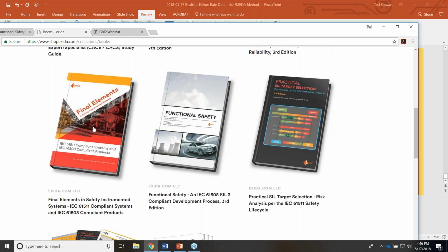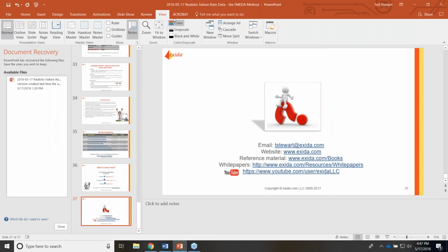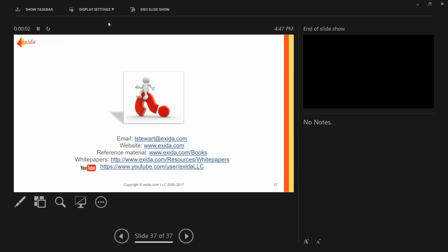And right now we even accept, well, I don't accept, but end users even accept that a valve leaking is okay. No, how do we solve a leaking valve? And right now, with a lot of pressure, maybe it's not possible. So we're even diving into torque specs, and this book actually talks about different torque specs, and really starting to analyze and try to make the Final Elements not your weakest link anymore. Of course, that's an uphill battle, but it's fun trying to solve these types of things that we're seeing, if that makes sense. So good question.